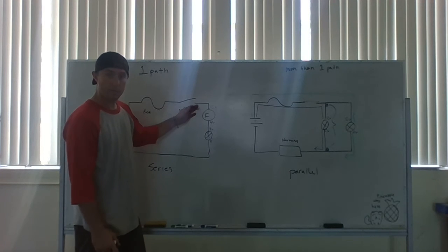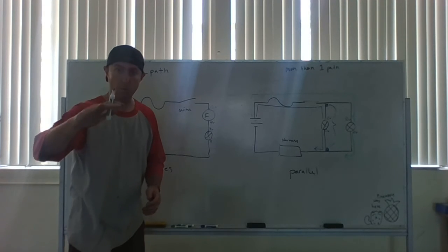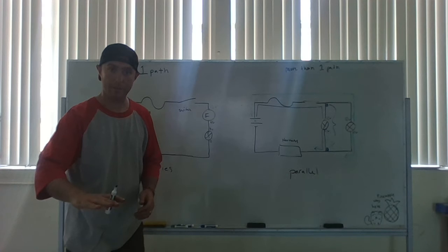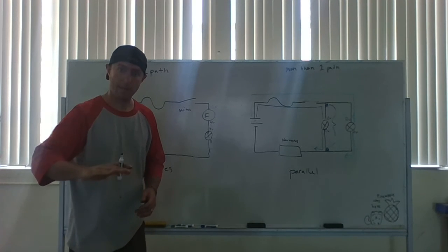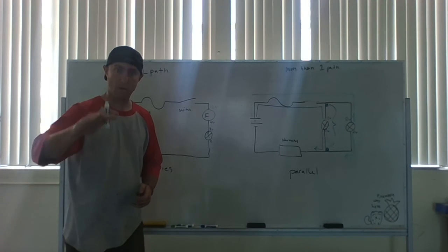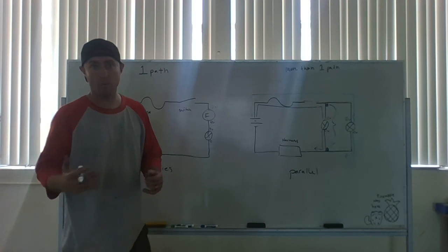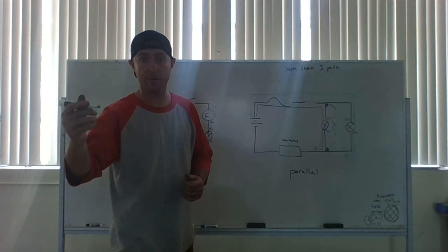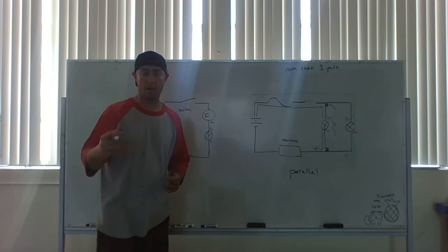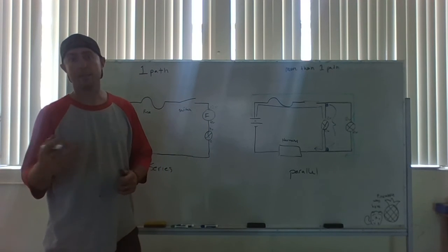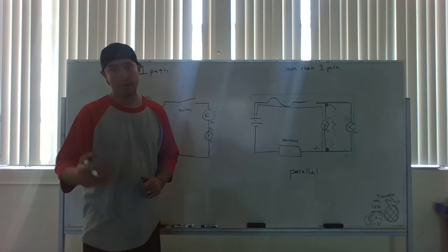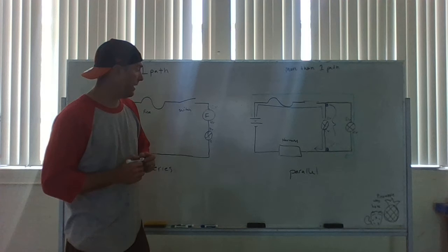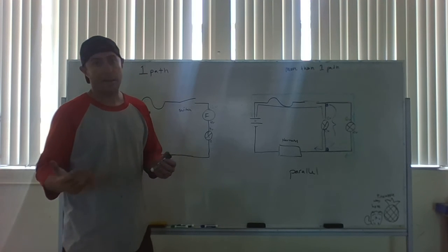So the reason I just want to point this out is that it's not always an equal voltage drop going down the path. It depends on the component. It's only equal if it's the same thing all along the line. Then it's an equal drop all the way down. Some things pull more, have higher resistance than others, and therefore you have a larger voltage drop. Things like fans, electric motors, stuff like that are going to have a lot. A solenoid may have a lot, but then things like a light bulb, not so much.